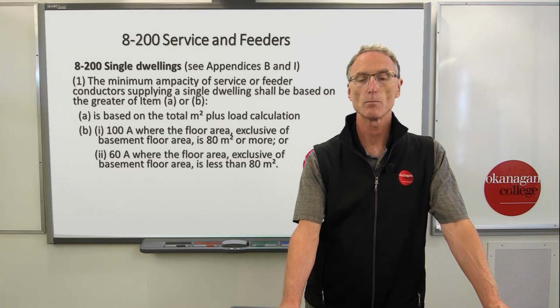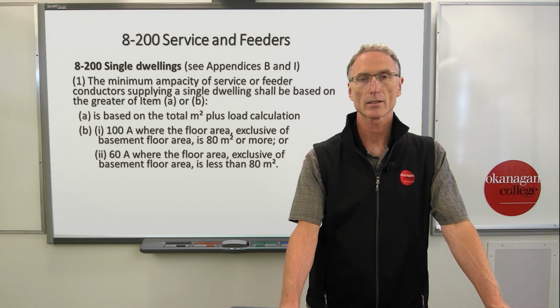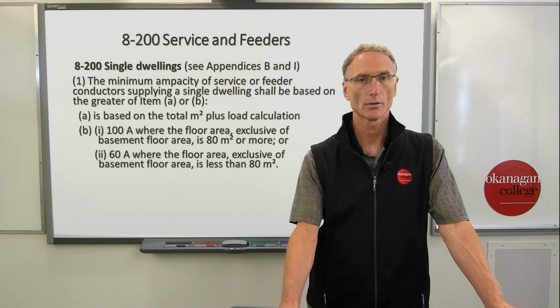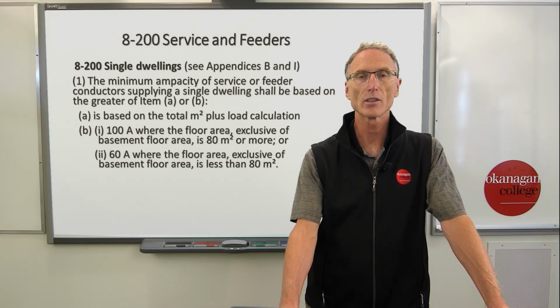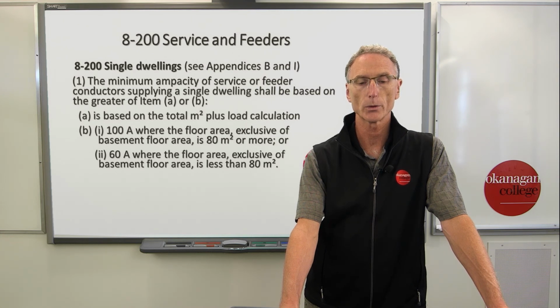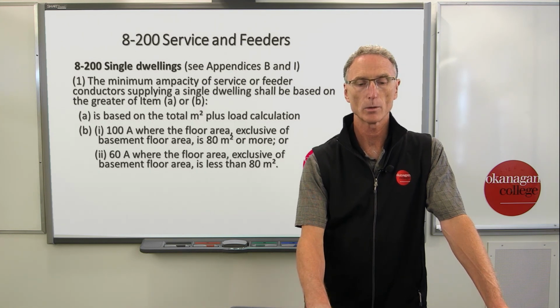So the total dimension of the house, that's called our basic load. That takes into consideration the lights, the plugs, the fridge, and so on. Any of the loads that are 1,500 watts or less. Anything greater would be the additional loads, and as we have seen, that's what we're going to go through here, this calculation. And of course, B is the very minimum that would be required.